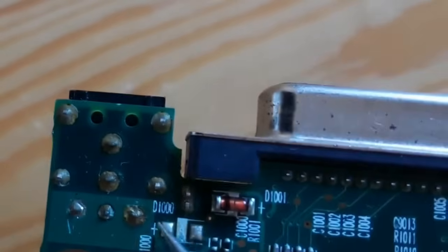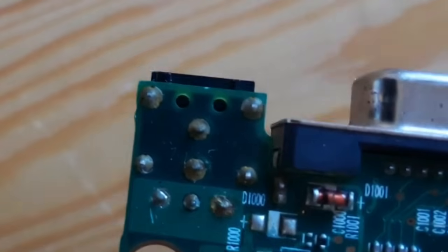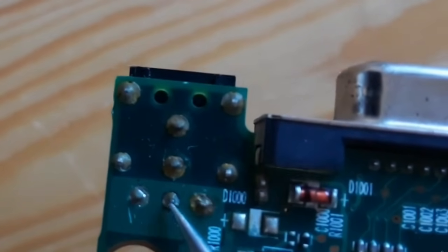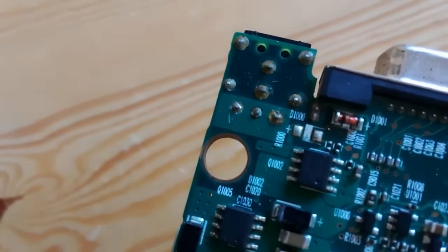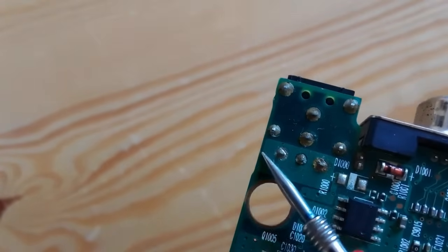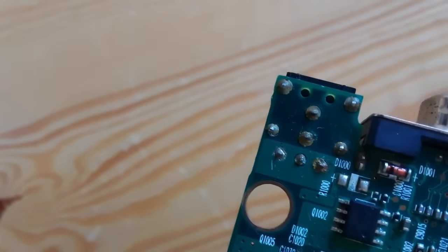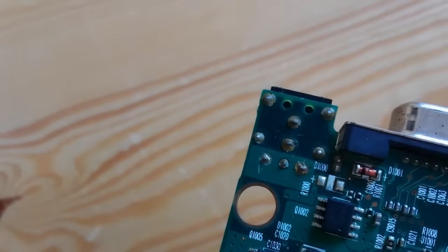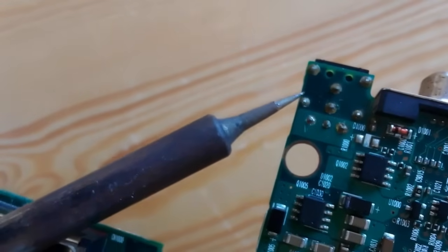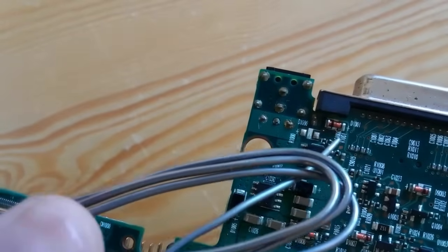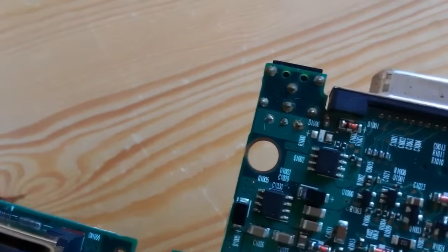On the back of the power jack, on the other side, here we have the terminals or pins. You should always check the soldering. The soldering should be good. If there is a dry joint in any pin or terminal, you should make another solder. As I told you, the power jack is among the common faults of failed laptops. To make a new solder, you can just use the soldering iron and the solder to make a good contact.